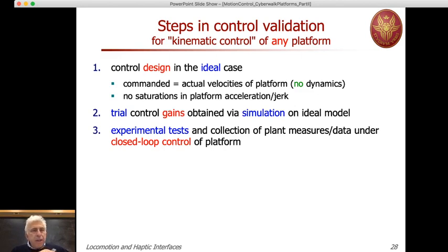You know that identification of the actual dynamics of the system can be done open loop, so you generate commands and you collect data and you try in a parametric model to fit the best parametric values that reproduce the data that you have collected in your testing experiment or identification experiment. Here you do exactly the same, but you apply already your target controller with some nominal, the best parameters that you have. This is good and bad.